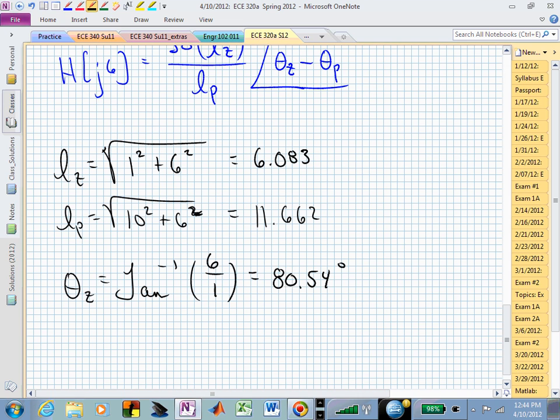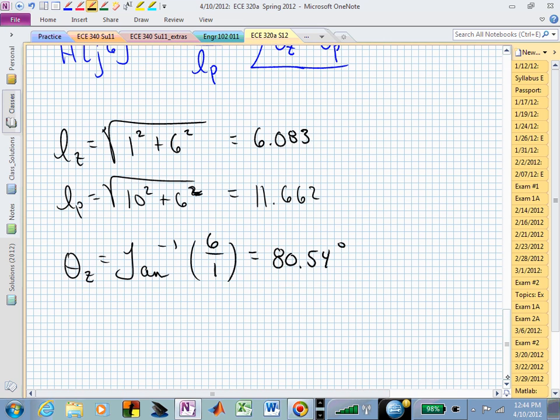You would have to be looking all the way up. As you get way up there in frequency, that zero is effectively contributing 90 degrees. Likewise with a pole. A single pole can contribute 90 degrees, it's just in the basement, and so it will be minus 90. That's what we need to work on understanding when we start sketching these Bode plots.